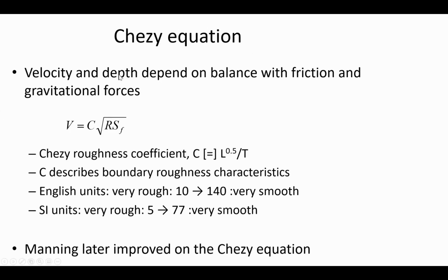All right, the Chezy equation is kind of a historical friction loss formula that for the most part people have moved on from, but it's important for you still to be acquainted with it because you may occasionally run across, for example, drainage networks that were designed using some of these older friction methods. It's helpful to understand a little bit more about what engineers assumed in those days to be able to understand why pipe diameters are sized the way that they are, for example.